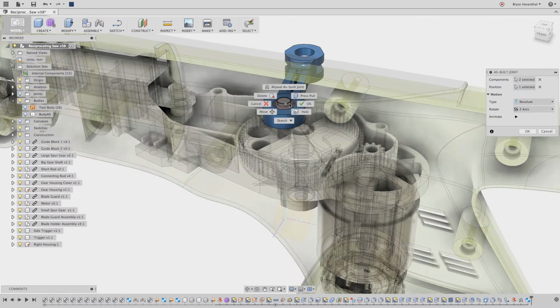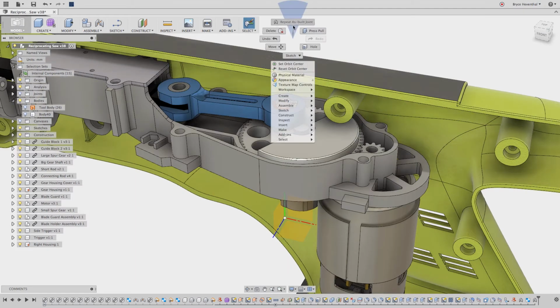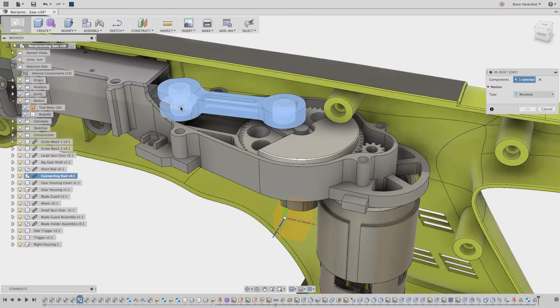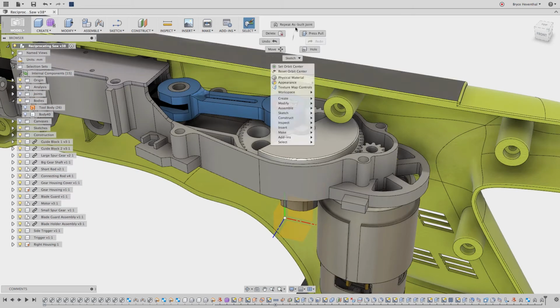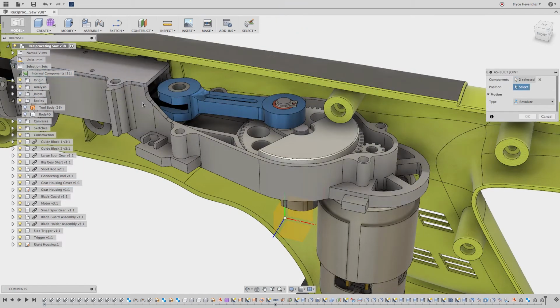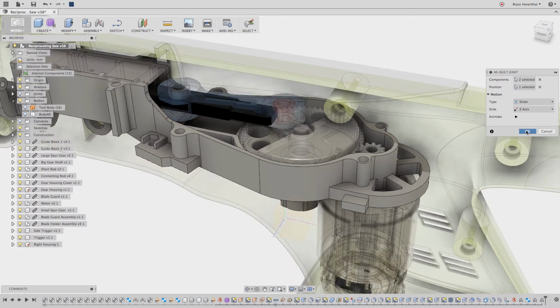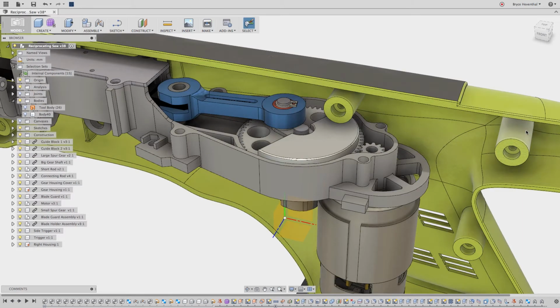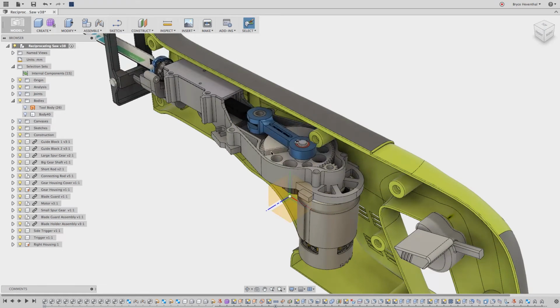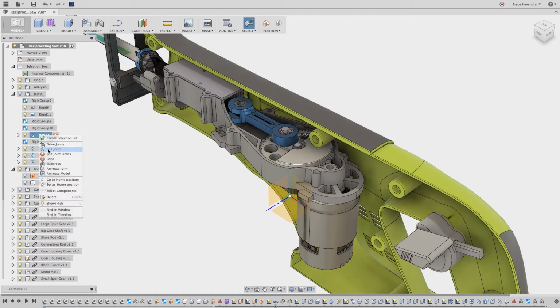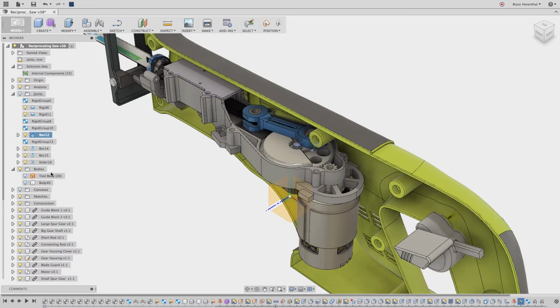In traditional CAD, when mating or applying constraints, usually an engineer is trying to lock down the 6 degrees of freedom, 3 translation, and 3 rotation. This usually takes 2 to 3 constraints or mates to get the desired motion. In Fusion 360, we apply one joint. We lock all 6 degrees of freedom down and change the joint type to get the desired assembly motion. This will help designs get assembled faster and behave more robustly when design changes are made.